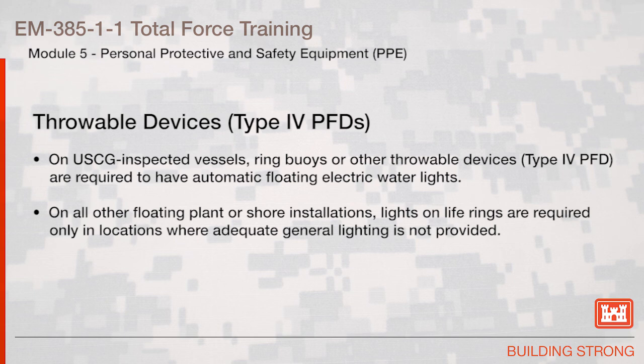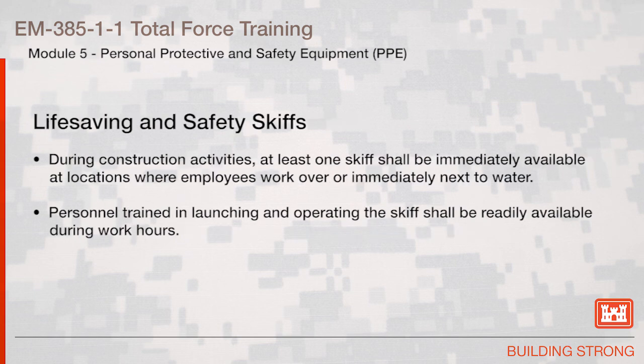On all other floating plant or shore installations, lights on life rings are required only in locations where adequate general lighting is not provided. During construction activities, at least one skiff shall be immediately available at locations where employees work over or immediately next to water.